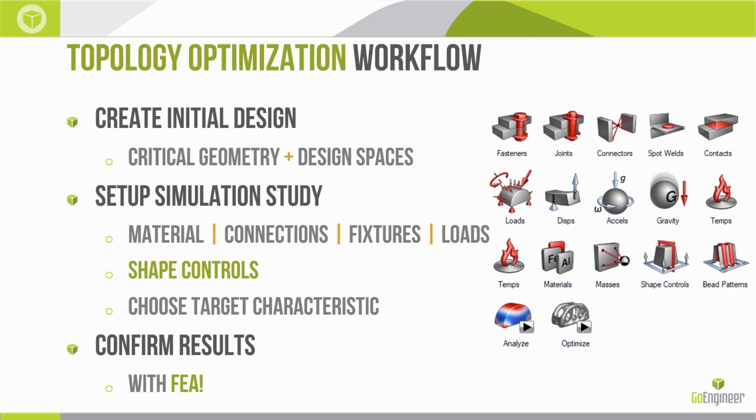And if we are designing for additive manufacturing or 3D printing, then that might be a potential solution for us. But the vast majority of parts today are still manufactured in conventional ways, things like machining or casting or molding or extruding. And each one of those methods of manufacture are kind of geared towards different types of shapes. If we're molding or casting, we might need some draft in one or two directions. So these are shape controls.